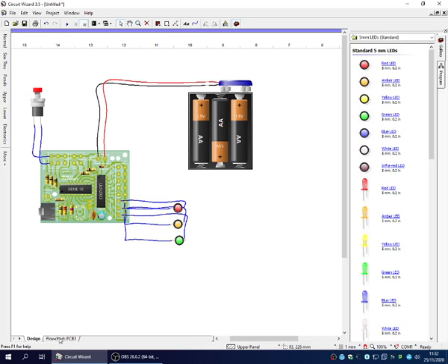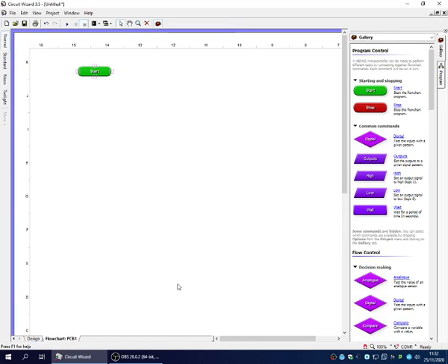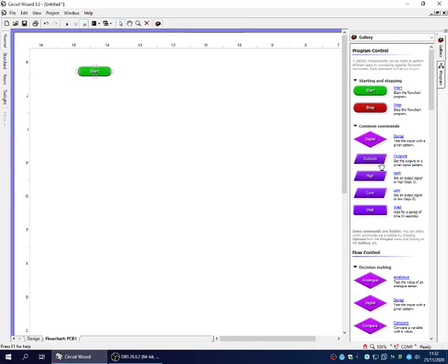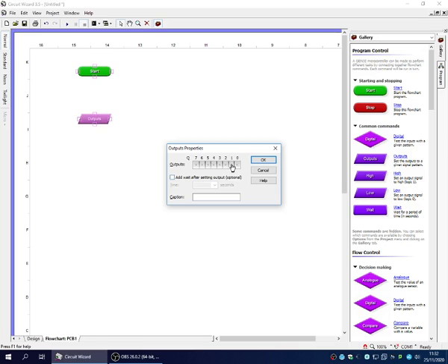So down here on this tab, you've got flowchart. This will be tailored to whatever we've dragged onto here. So if we use the Genie 8 with fewer inputs and outputs, when we look at outputs, for example, we're going to have the corresponding number to which the chip is. In this case, we've got all 8 outputs here.